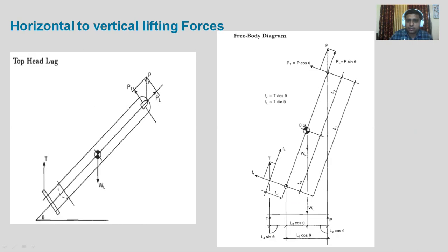So as we are going to have the lifting lug and tailing lug in equilibrium condition, these forces will be balanced by two reactions. One is the tailing lug reaction in counter direction. This is downward, this is upward, and another is the force P. Correct? So for this CG, there will be a vertically downward force, and at the tailing lug, there will be a counterbalancing force. It is in vertical direction, and here the P force will be in vertical direction.